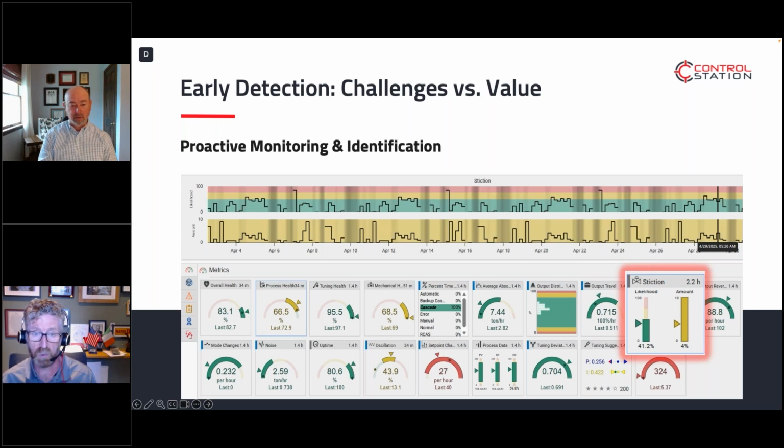But more importantly, there's specific periods throughout this time period that we're looking at here showing significant amounts of stiction, I suppose. There are some that are quite excessive and there are some that are small, but in this period where you see the slider bar in the top right corner, if you look across, there's at least 4 different instances of this same type or amount of stiction. So quite clearly you can say, okay, we do have significant stiction.